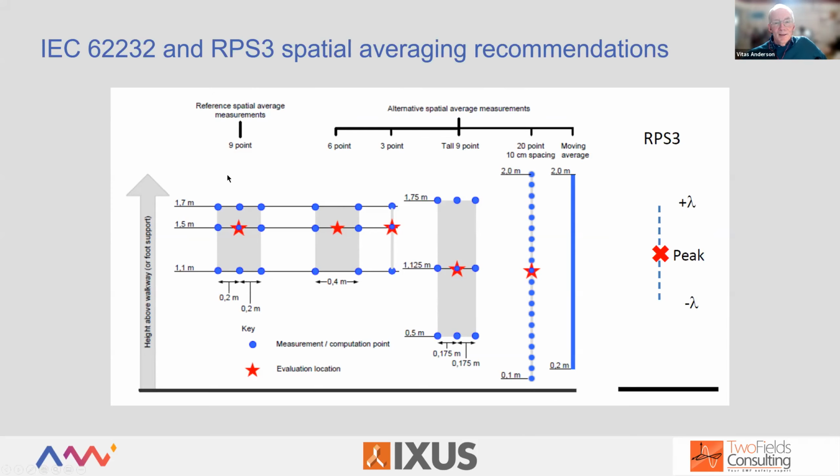Now, our AS/NZS 2772.2 standard for doing EME assessments refers to the IEC 62232 standard in terms of recommended spatial averaging schemes. I've just displayed a copy from some work that Steve Iskra presented probably 5 or 6 years ago. You can see they're vertically averaged schemes, but not actually averaged over the entire body space. They have averaging points around the upper body, but not the lower body.